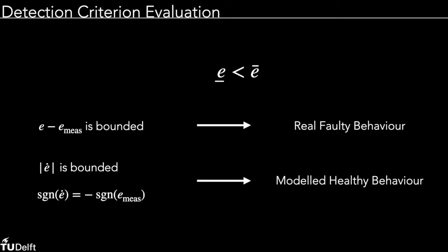If a fault occurs, the real and model system behaviors will contradict each other, and therefore this condition might no longer hold in a faulty situation. Using this condition, we eliminated the filtering required with the detection methods from previous work, and we gained the speed that is required to consistently detect all oscillatory fault cases.